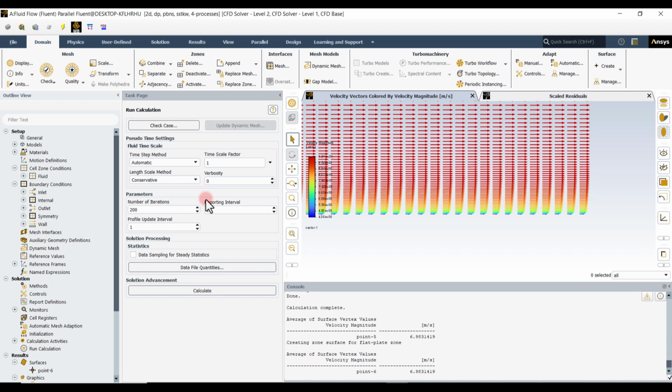So Blasius doesn't work anymore here, but still we only reached 20% error. So you have to decrease the inlet velocity in order to keep the laminar flow regime and prevent any transition to turbulent flow. And then you can investigate the Blasius solution once more. And these are just two main reasons for this 20% error.